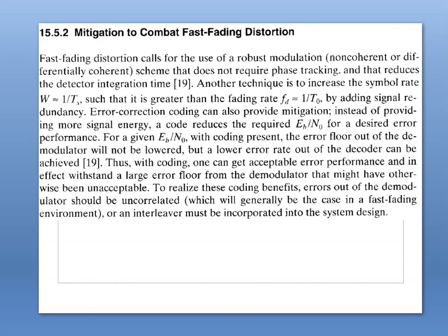A polyphase filter technique is also used to provide time domain shaping and partial response signaling, in order to reduce spectral sidebands of the signal, which helps to provide orthogonality. The process introduces ISI and adjacent channel interference, which are then removed by post-processing equalizers and cancelling filters.